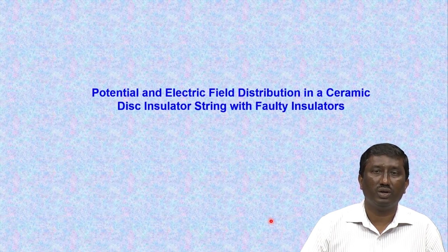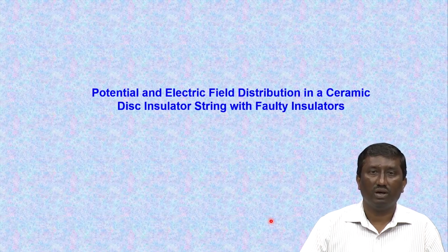If there are 24 insulators in a 400 kV system, and you happen to see physical failures at particular locations, whether the entire power supply has to be switched off to replace the insulators immediately, or it could be left for some time. Taking this decision by the utility engineers is very important. So, we have tried to analyze the failures or discs which are faulty in nature, from a very low voltage to the ultra high voltage strings. So, we will be looking into this.